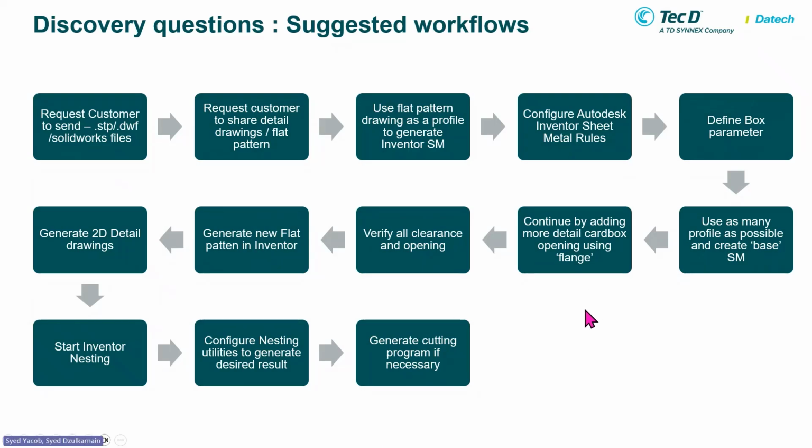So usually in this industry, it's quite straightforward: we just receive drawings or designs from the customer, or probably this is all done in-house. Usually we as a designer or engineer request sheet metal drawings, or sorry, flat pattern drawings if there are any. If not, any measurements of the products will do, and then we repurpose them and make our own so-called flat pattern. So we are going to use sheet metal flat pattern to generate a flat pattern for the boxes, so that we can later simulate the cutting.